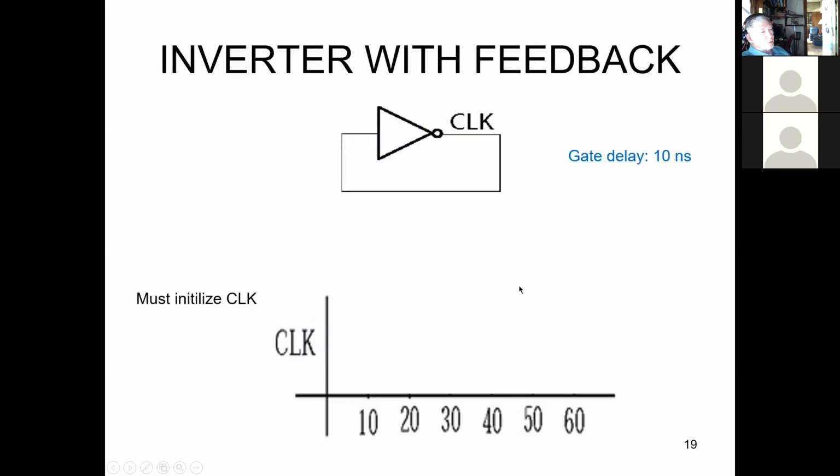All right. This is a confusing slide because you can only do this in your test benches. This is what we do to create a clock in our test benches. So we don't put this in our Verilog code. We put this in our test bench code to exercise our code. If you really synthesized this for real, you would have no idea the speed at which it would work, because you're not guaranteed these gate delays. And also it wouldn't be a perfect square wave. It'd be all screwed up.